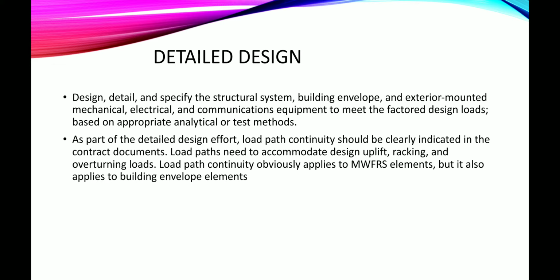Detailed design. Design, detail, and specify the structural system, building envelope, and exterior mounted mechanical, electrical, and communications equipment to meet the factored design loads based on appropriate analytical or test methods. As part of the detailed design effort, load path continuity should be clearly indicated in the contract documents. Load paths need to accommodate design uplift, racking, and overturning loads. Load path continuity obviously applies to main wind force resisting system elements, but it also applies to building envelope elements.